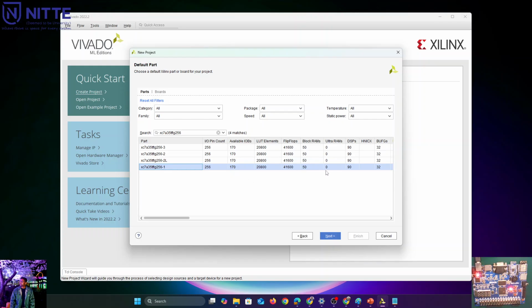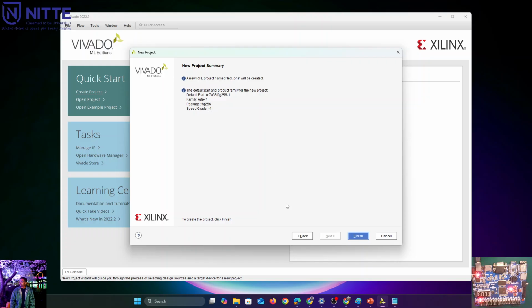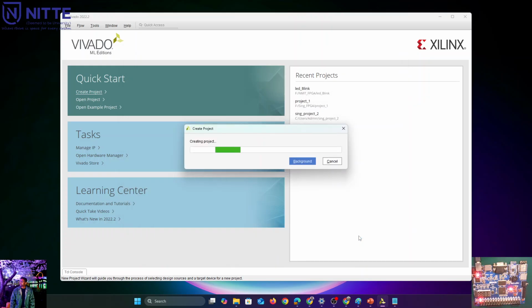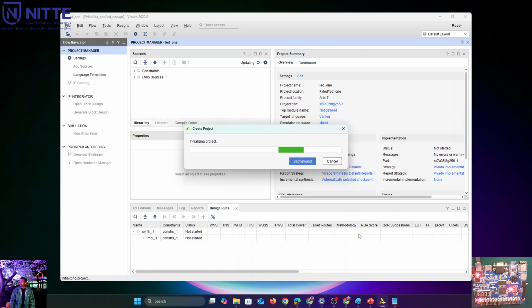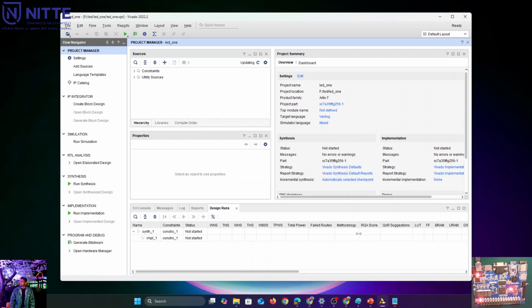So how many LUTs, flip-flops and block RAMs are available? You can see the detailed things. This value I got just by capturing the image you see in the hardware I showed in the pin point. So here we can capture and then we'll get this data, select this, click next, and click next or finish. Now this will make a project file for our particular FPGA IC.